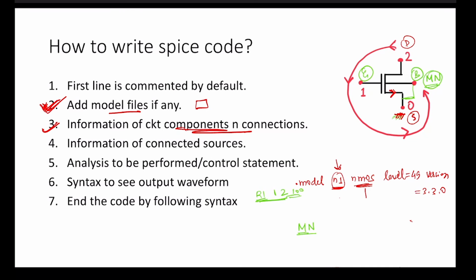So now this MOS is connected between, I'll tell you, suppose it's a complex circuit. Suppose there are 2, 3 MOS stacked together. So we need to assign numbers to all of them, and we follow this convention. See, I have made a mark here this way. So we start from the drain. We will write the drain node, 2. After drain, the gate will come. The gate is connected to 1.